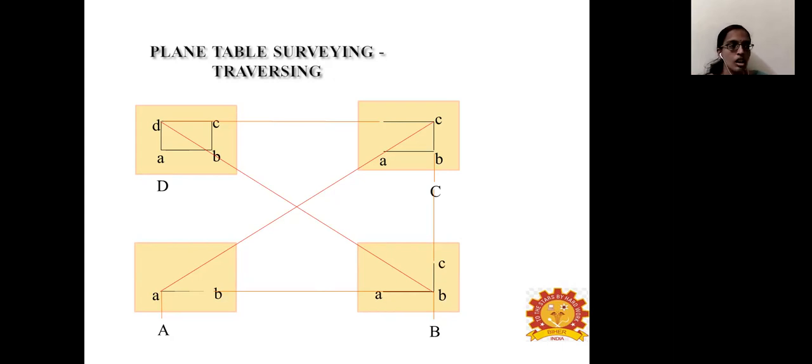What are the components used for this technique? One is the spirit level, second is the plumb bob, then the table, the drawing sheets, sighting vanes, and compass. These are all the equipment needed. The compass indicates the direction, the north and south direction, known as magnetic north and magnetic south. Thereafter we can mark the east and west positions.